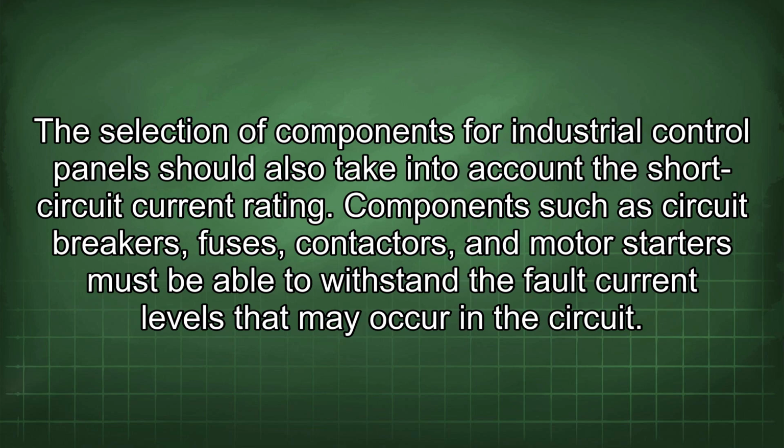The selection of components for industrial control panels should also take into account the short-circuit current rating. Components such as circuit breakers, fuses, contactors, and motor starters must be able to withstand the fault current levels that may occur in the circuit.